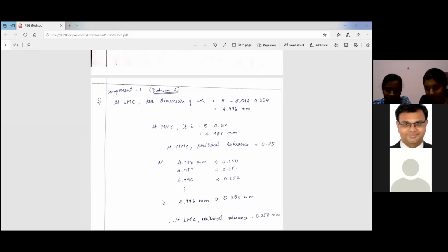So here 0.25 is the position tolerance. You also see the question parallelly. Yes, sir. 0.25 is the position tolerance when the value is in the maximum material condition of 9.65. So when you go from 9.65 to 10, it's almost 0.35 increase there. So 0.35, when you add it with 0.25, it becomes 0.6.